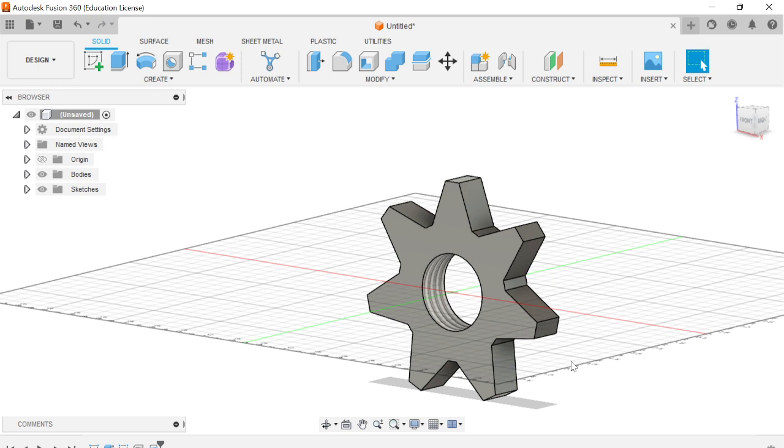Yeah, okay. So why that happened was, notice where this dimension is. Your dimension, that point to that point, if you're saying that's 2 inches, whenever you go to extend, you are moving that point downward, and that 2 inches no longer holds true. So you need to just redimension it. Right? You can't be doing it, you're breaking the dimension. So you extend it, and then just